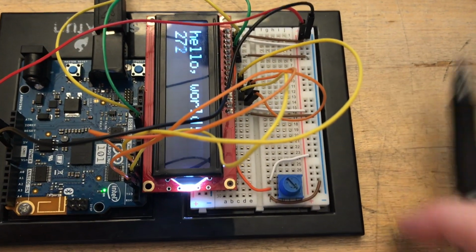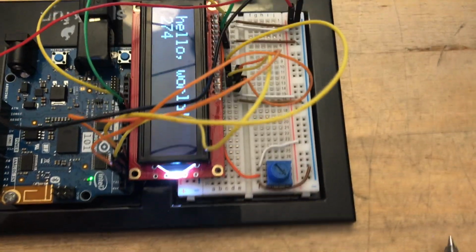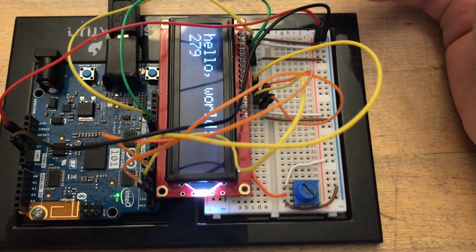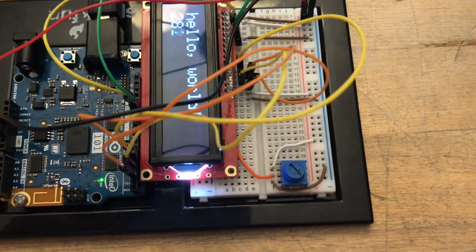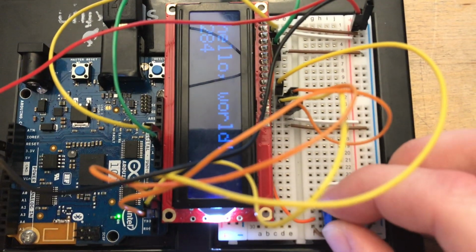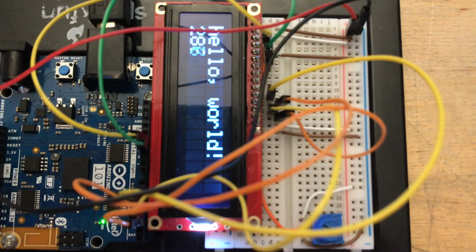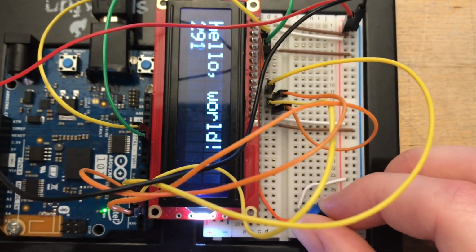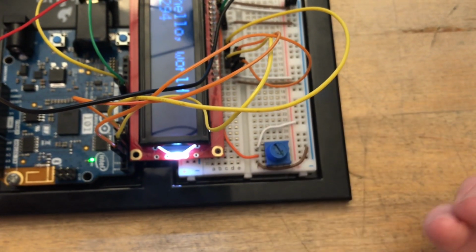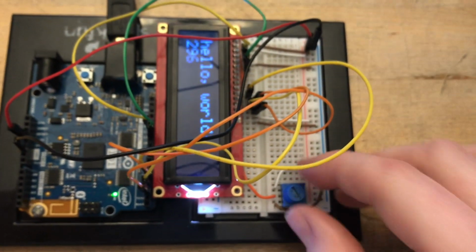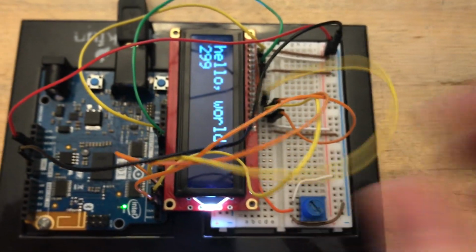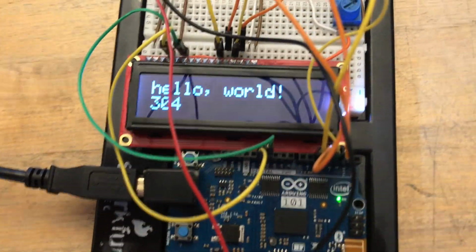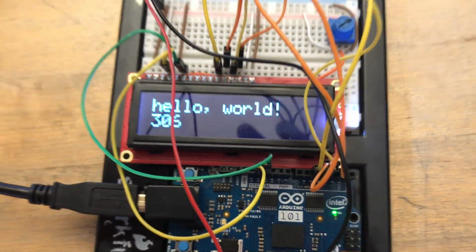And so then how the LCD screen works is there's a total of 32 possible characters on the board. That's made up of 2 rows here, and on each row there are 16 possible characters. And we can see that if we turn the contrast all the way up, we can see the different boxes that can contain characters. And then the LCD is controlled through the library that we use in the code. And so that's it working. It says hello world, and it's counting the seconds up for us. There we go.